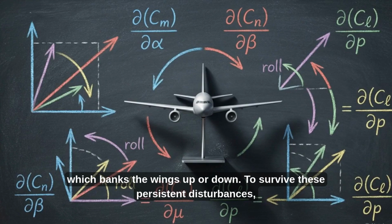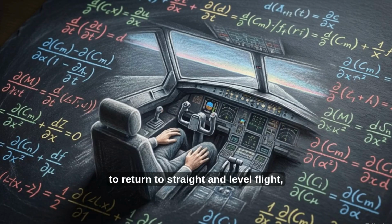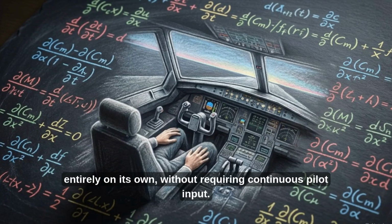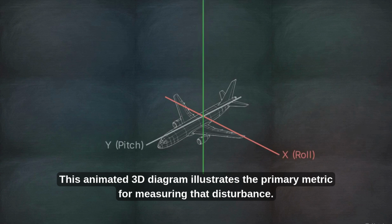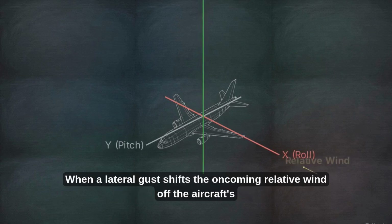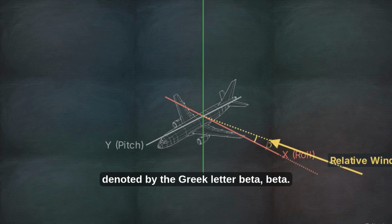To survive these persistent disturbances, the airframe must possess a natural geometric tendency to return to straight and level flight entirely on its own, without requiring continuous pilot input. This animated 3D diagram illustrates the primary metric for measuring that disturbance. When a lateral gust shifts the oncoming relative wind off the aircraft's center axis, it creates what is known as a side slip angle, denoted by the Greek letter beta.